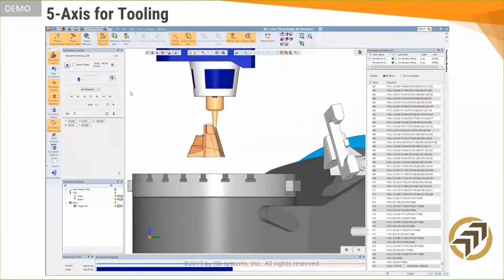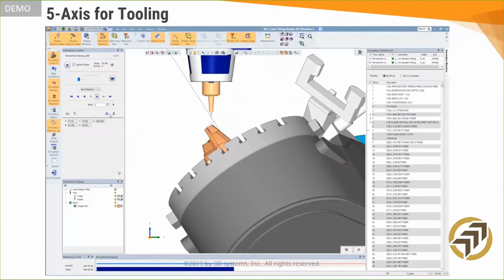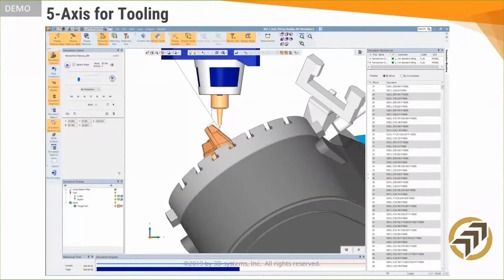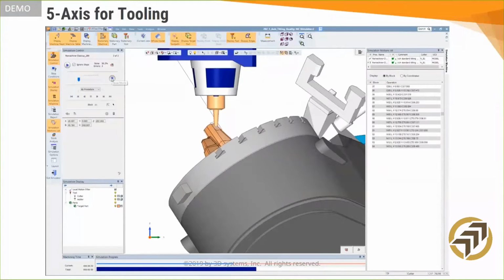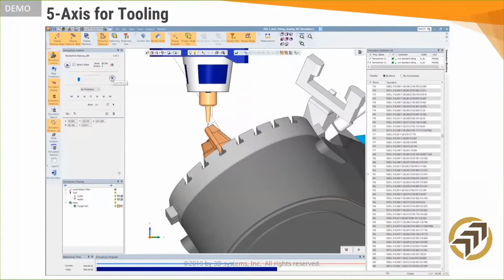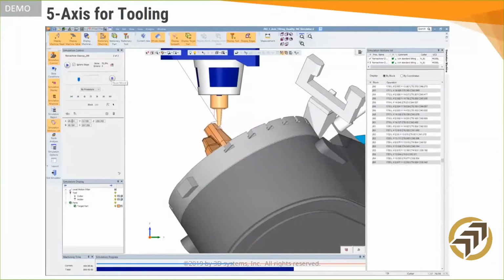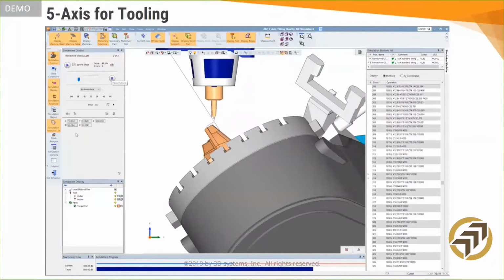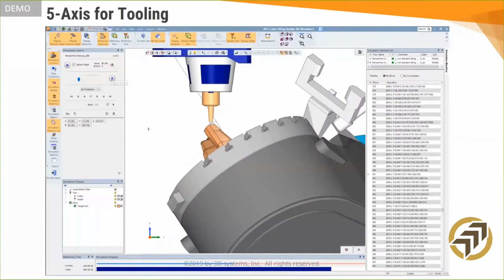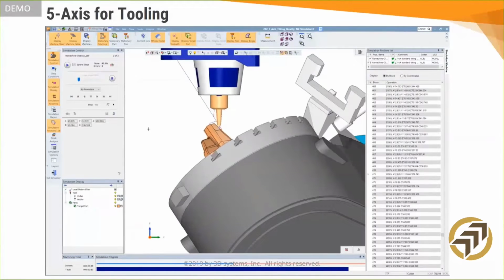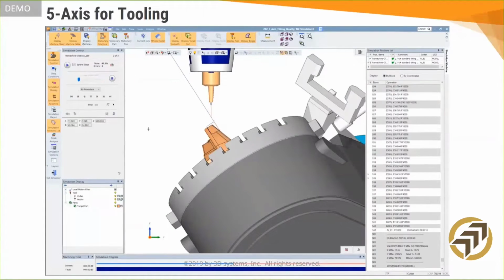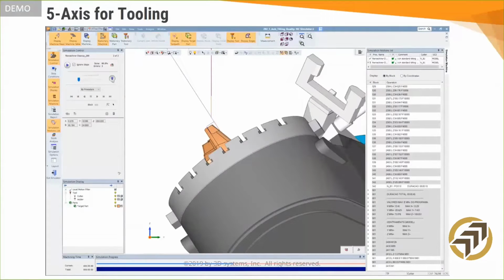Automation can even be applied to 5-axis machining. For example, cleanup or finishing routines that were programmed in a regular 3-axis way can be simply switched over to 5-axis with automatic tilting. And if more control is desired, a host of other options can be brought into play to minimize rotational movement or just provide a more stable tool path with the user preferred motions.